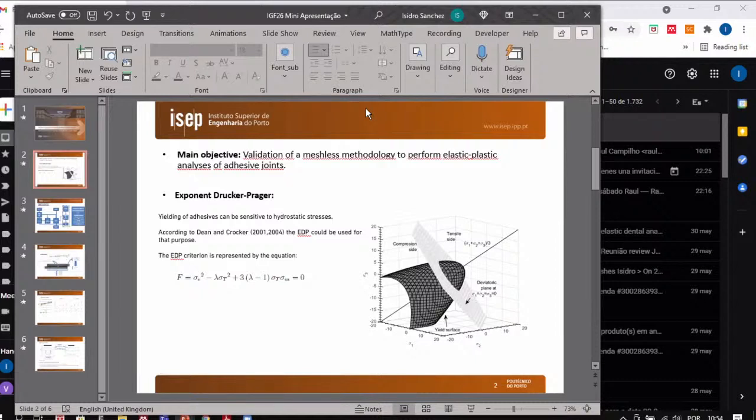In this case, we're using an interpolation method, the radial point interpolation meshless method. It's not a new method. It has been around for perhaps 18 to 20 years. However, this method in particular has the advantage that it's quite accurate, and quite well spread in the literature. Therefore, what we do here can be easily applied by other research groups around the world, in contrast to more recent meshless methods that are quite particular to some research groups.